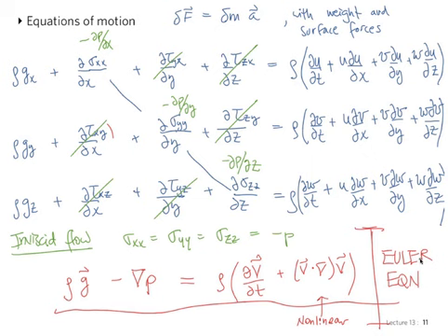The Euler equation is the specific case of the equations of motion in differential form for an inviscid fluid. Also, we assumed constant density. And this is where we left off, this special case of inviscid flow, where we have no shearing stresses.